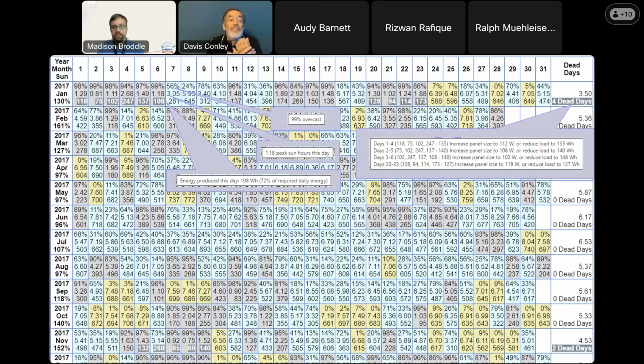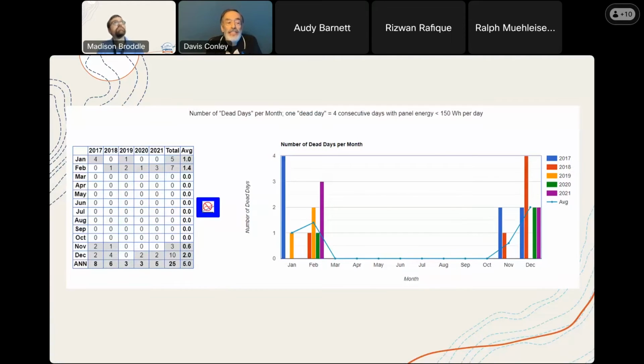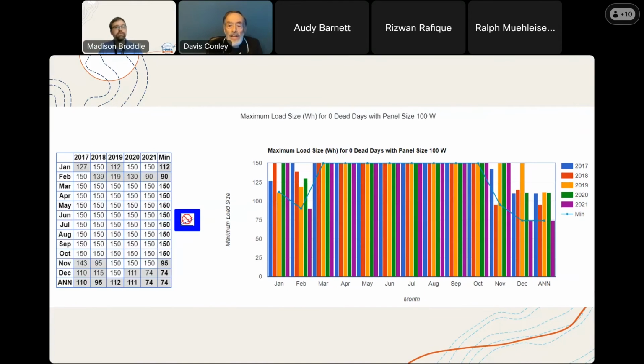Next slide, please. And it shows you here that in January of 2017, there were 4 dead days in that particular month. And on average, for this 5-year period, you had 5 dead days per year. And next slide, please. I also worked the calculations backward to say, okay, given that my panel size is fixed and my loads are fixed, how can I reduce my dead days to 0, which of course is what you want to do.